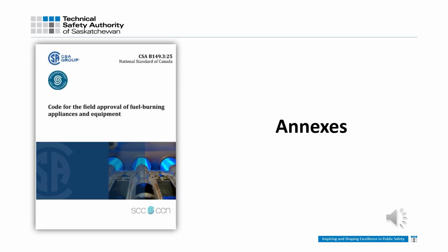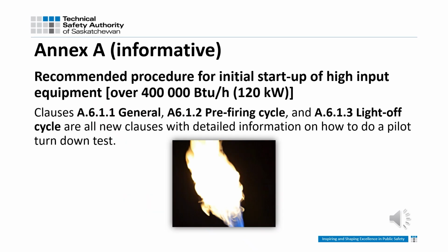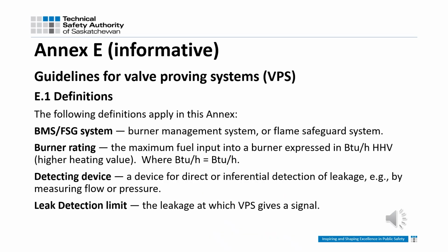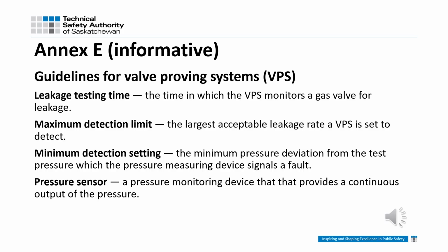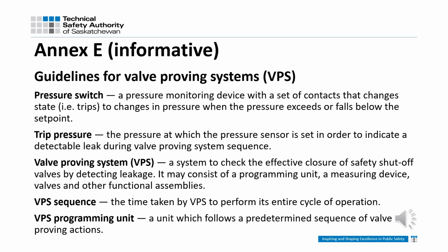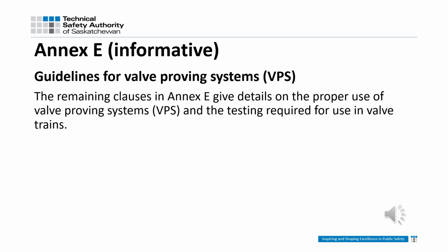Annexes. Annex A has been rewritten to give more details on how to perform a pilot turndown test. Annex E, Guideline for Valve Proving System, or VPS. E1, Definitions. More definitions. And yet more definitions. Annex E lays out proper use of VPS and testing requirements.